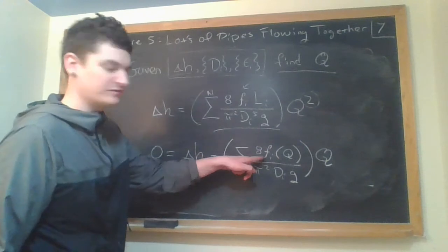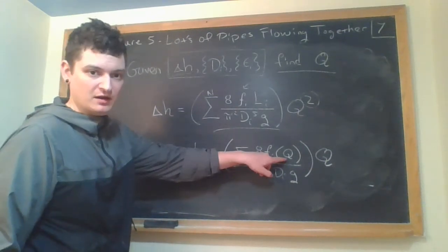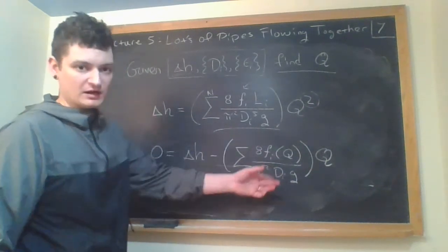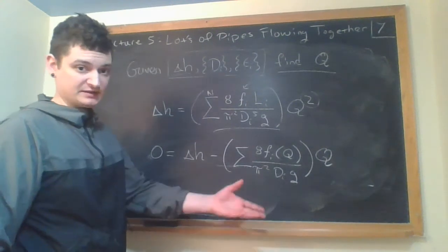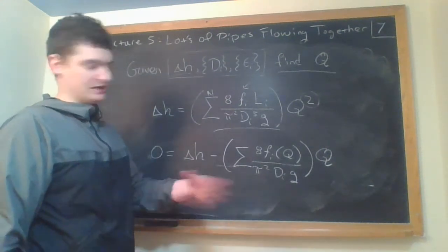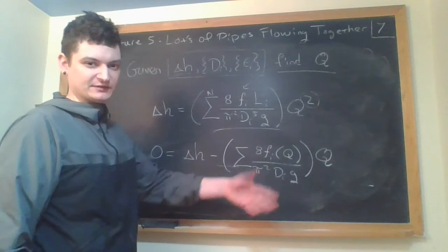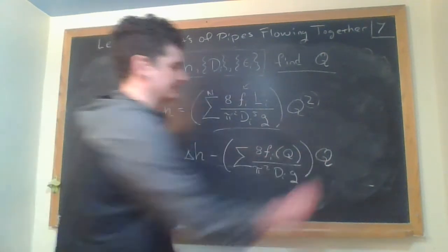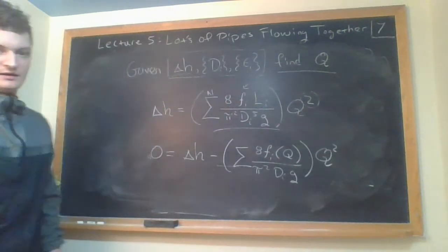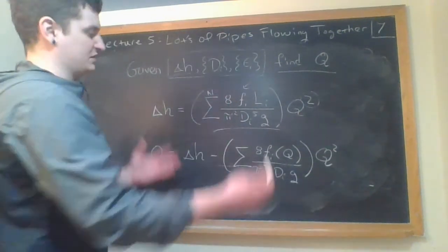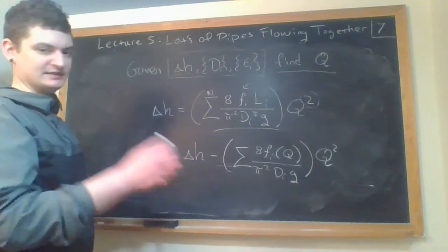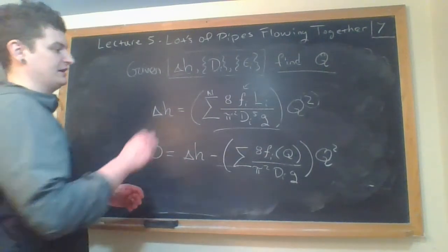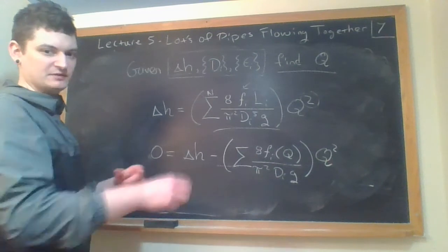See, I put how the friction factors are functions of the flow rates themselves, because the flow rate can be solved for velocity, and the velocity is needed for the Reynolds number, right? And then even the diameters are in there, but you know that. So that's that part set. But the thing that's not is that this is a function of this, right? But Jerry wrote out these methods where you could actually just do this iteration of, calculate it for a guess and then do the same thing over and over again.